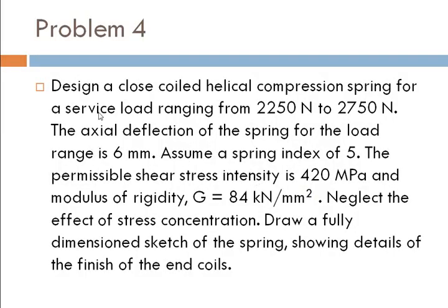Next, see problem 4. Design a closed coil helical compression spring for a service load ranging from 2250 newtons to 2750 newtons. The axial deflection of the spring for the load range is 6 mm. Assume a spring index of 5.